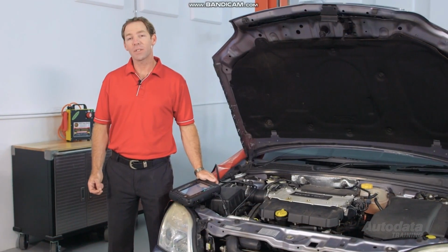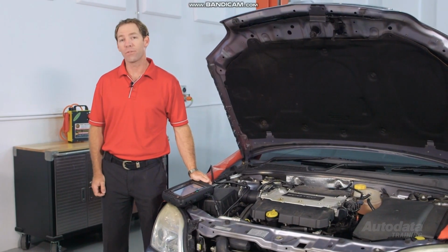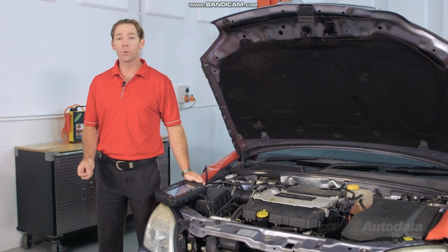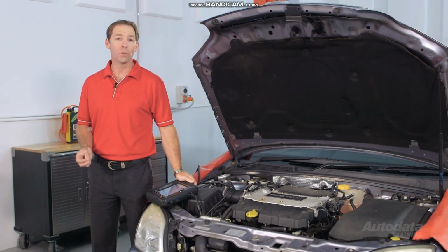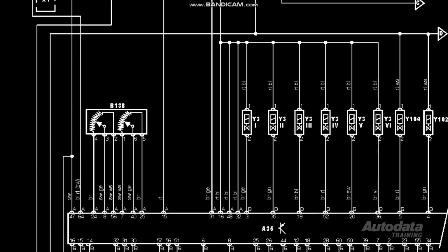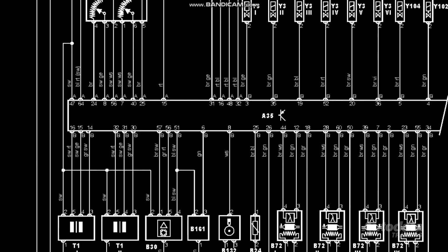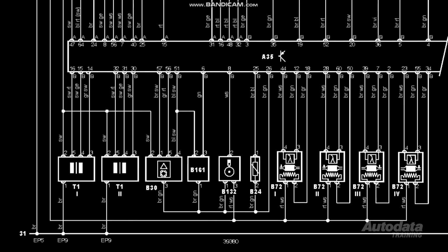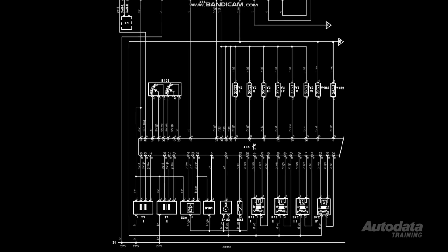Before attempting to test or diagnose a MAF circuit fault, a schematic for the vehicle should be accessed and referenced for system voltages. But some schematics won't tell you what type of signal circuit the engine management system uses. This is where an understanding of scan tool data is handy.